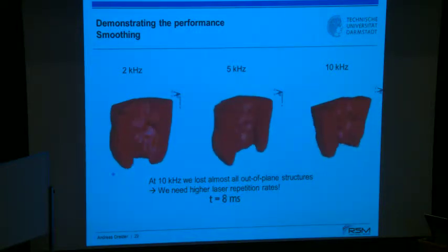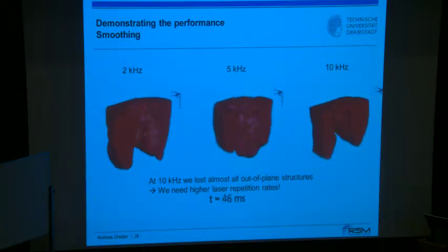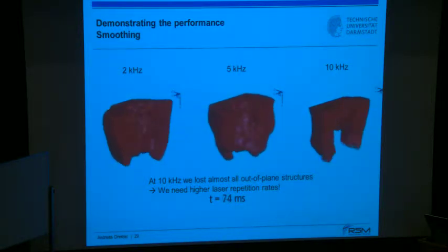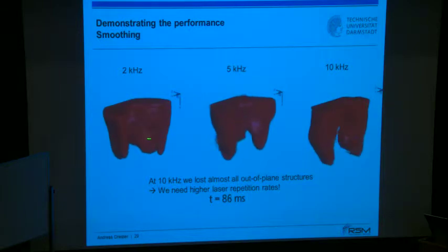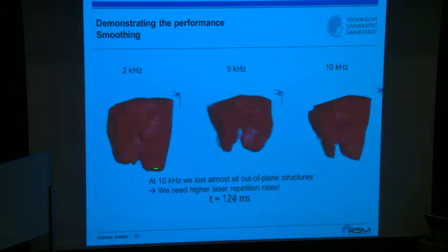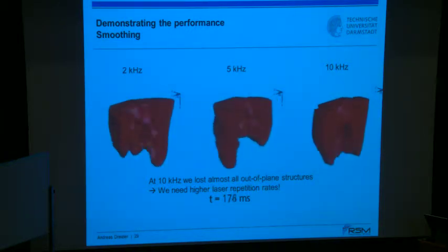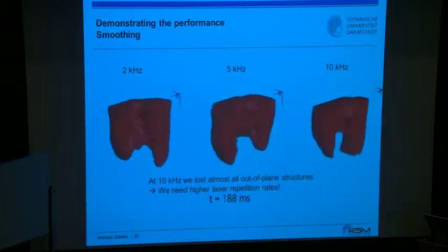If you now release your spatial resolution, and that has been done here, again, for these 3 examples. As you see, a lot of the structures that still have been seen at the 2 kilohertz sweep have now been removed. Everything looks now a bit nicer. Still, you can of course follow this leading edge that is, in slow motion, showing how the flame is competing against the approaching flow.